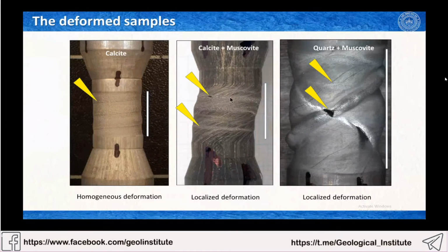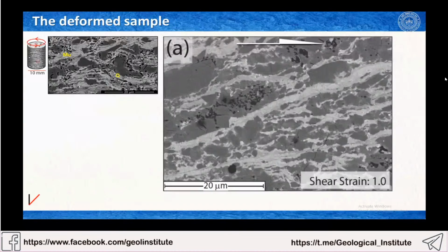But if you have shear localization, then because these are metals, they get hardened more, and you can produce some holes in the jacket, and if that happens, then you're gone. You have to stop the experiment because you lose the pressure very quickly. Luckily, we didn't have that in our experiments, so we could happily go to shear strain 15.